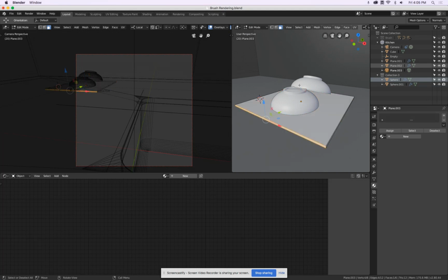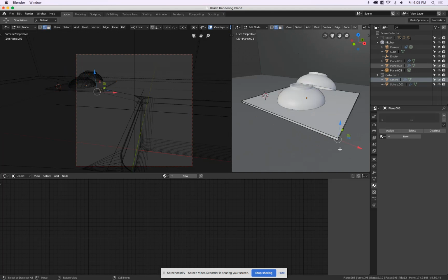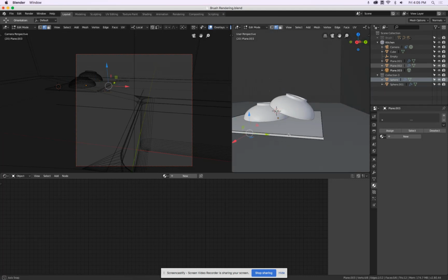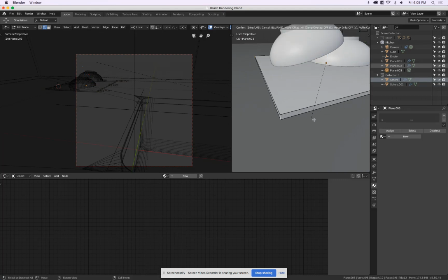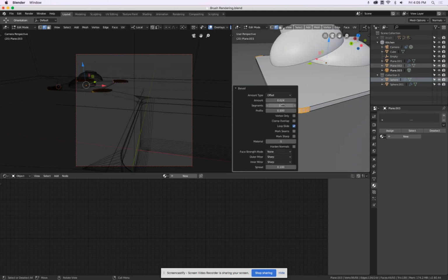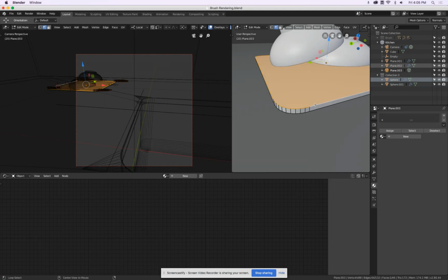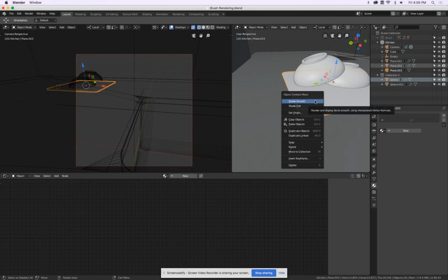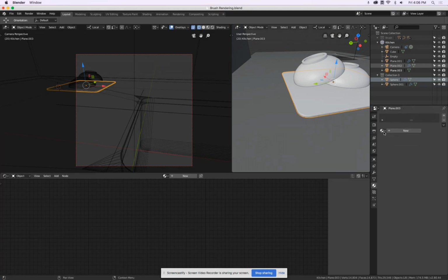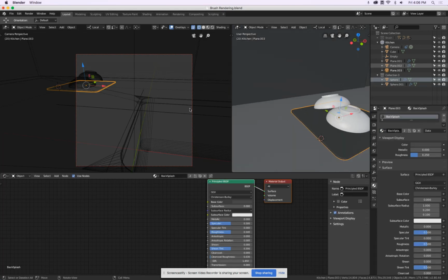And if you don't want to use the bevel modifier, we can actually use the bevel command, which I'm going to do now. I'm selecting all this, Control B, move my mouse away, move the mouse wheel, and then say here 10.55. And then I select this upper edge with Alt, Control B, and very gentle. Fillet that, Control, right click, Shade Smooth. We can make this backsplash. Let's take a look.